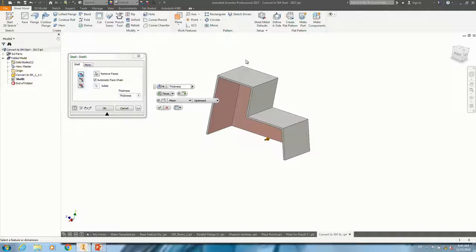Sure. I was concerned about it, but I also spent a lot of time testing it. So let's say you've got a quarter-inch plate, and you've got 5 of those with that distance defined in your sheet metal style. It basically will grab the first one on the list, and it gives you the opportunity to switch to one of the other ones as well. So you can override, or you can tell it which one you want to use. Otherwise, it uses the first one in your sheet metal style which matches that size. It works really well. Yeah, that's right.